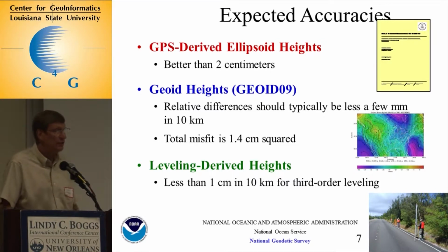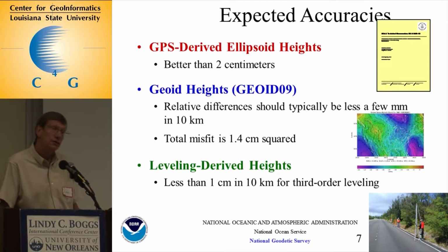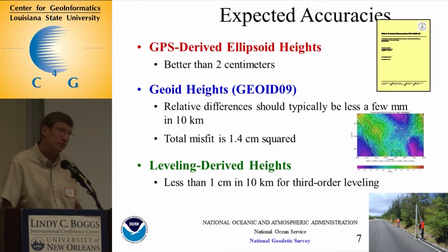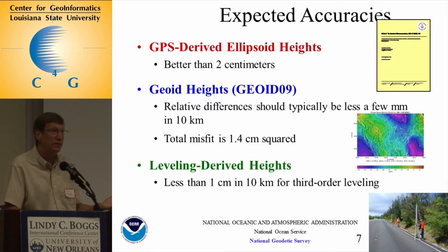And I had someone that called me up one time, and they had a problem with their GPS network. The heights weren't consistent, so I said, well, okay, first of all, did you follow the guidelines? They said, well, no, I didn't. I said, all right, well, tell me what you did. So when they were all done, they told me a lot of stuff they did with single baselines, and they occupied things twice, but there wasn't any way of checking repeat baselines. And finally, when I got all the information, I said, I can't tell you why you got a problem. I don't know how to fix it.